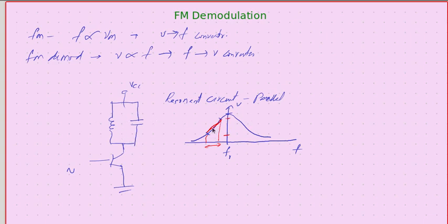And as the impedance at the collector is linearly changing in this region, that means if we have frequencies from say f1 to f2, which is what we had created for our input variations, and we feed this FM here, then the impedance keeps changing in this region, and hence changes almost linearly, and therefore we can predict the output changes linearly with respect to frequency.